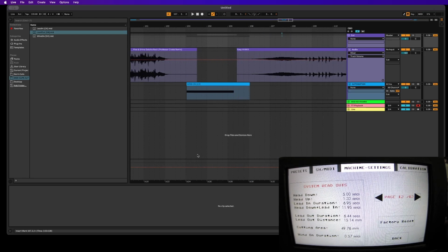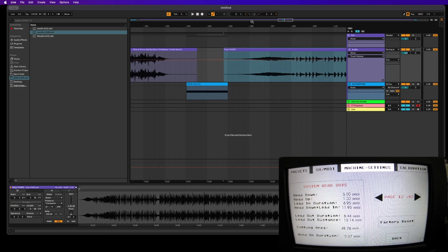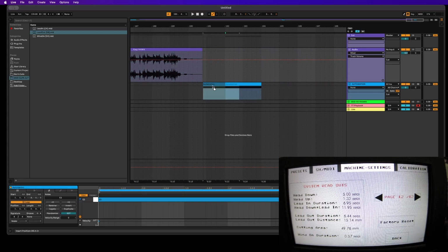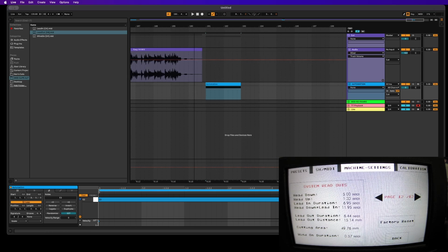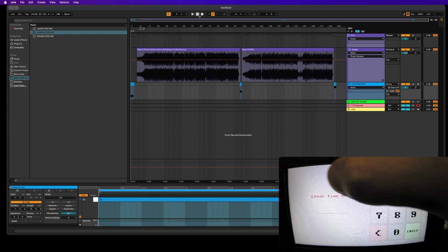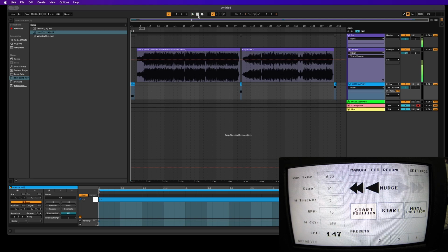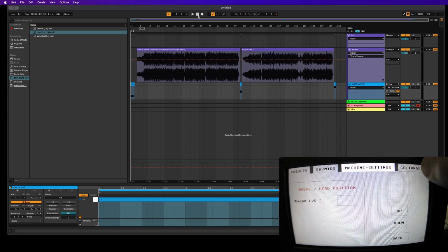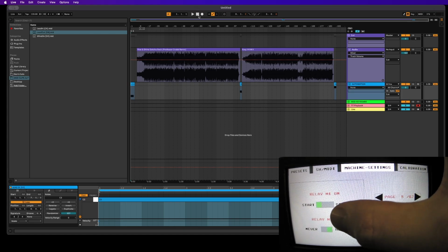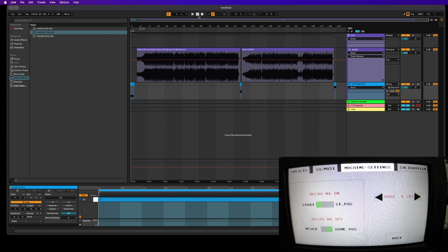There's a few seconds there between the tracks. The wind on itself is 0.57 seconds, but we always leave a couple of seconds between tracks. And then we'll just adjust the lead out where it starts. And we'll make that change in the program itself as well. So we'll also make sure the stylus heat is on, and you can see relay 1, it's going to activate when we press start, and then it will turn off when the head moves to the home position.